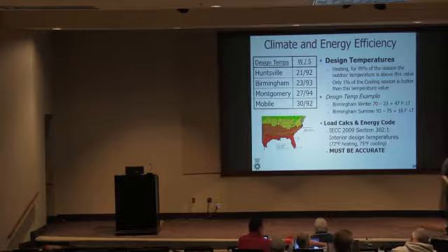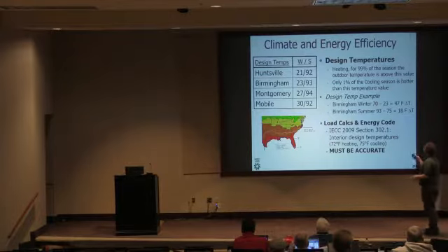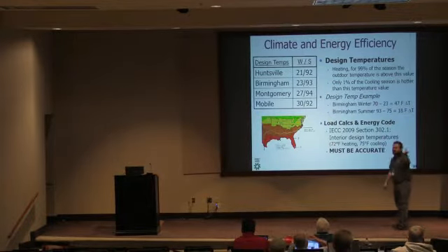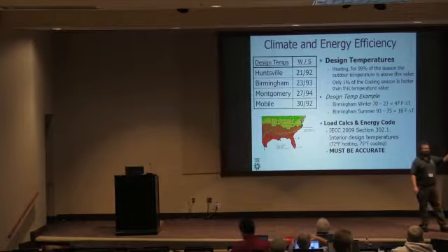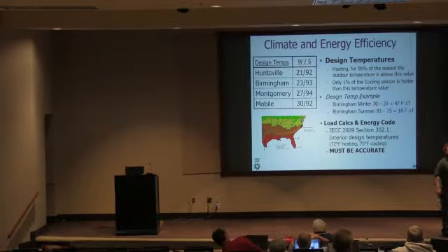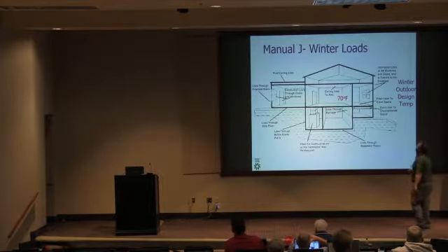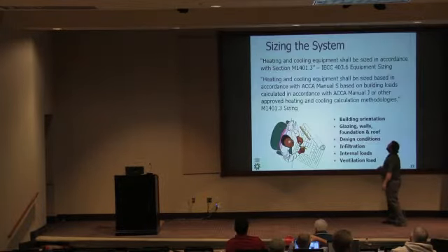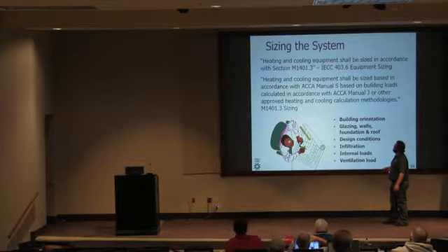And then look at infiltration rates. A tight house, which is what new homes are, is actually an input. You could go with a leaky house, and that's going to increase the size of the HVAC system. So design temperatures, surface areas, and leakage, infiltration on the home are the three easy things to manipulate on a load calculation if you're basically trying to make the software spit out a predetermined number. Just those things. All right.